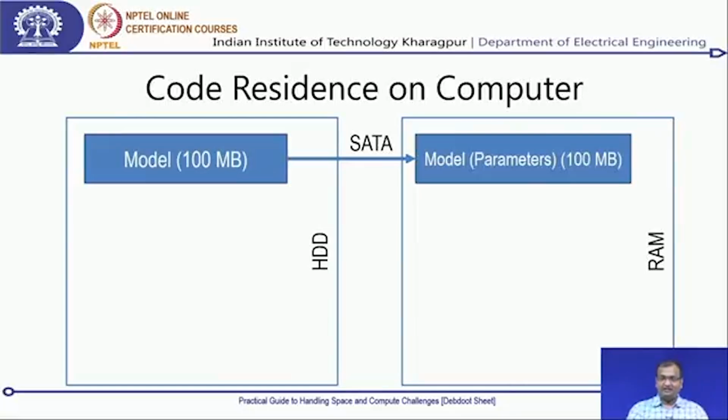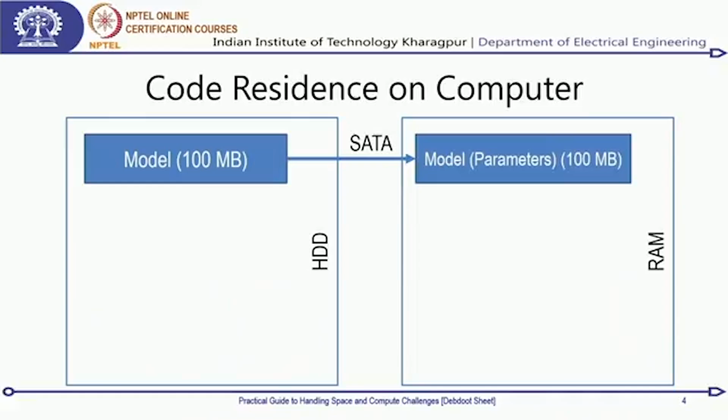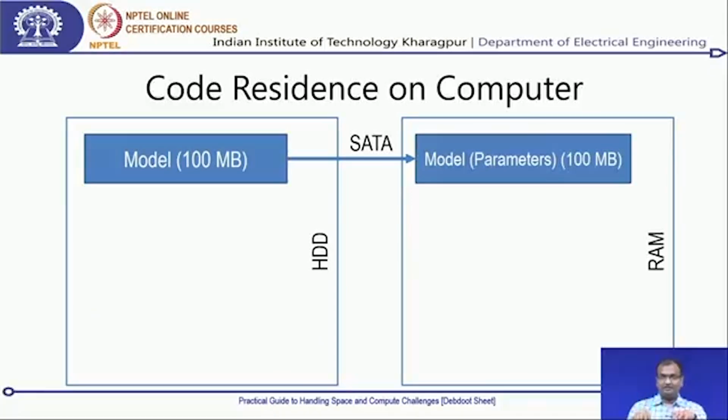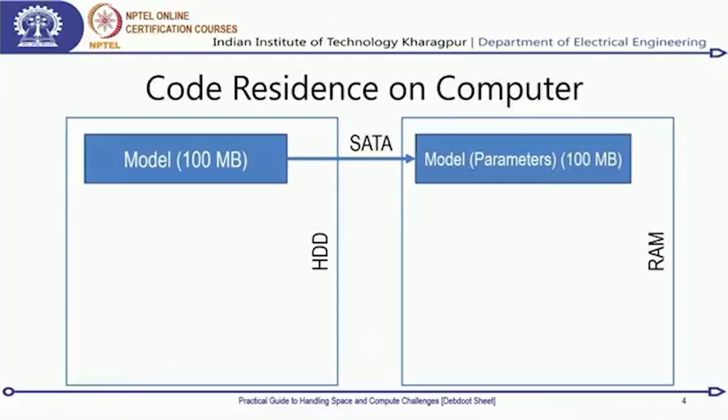So, what it essentially does is that there is a connection via a serial ATA. So, there is a SATA cable connection from your hard drive. It will be a thin blue colored or a black colored cable you would see, which connects from your hard drive onto your motherboard. Okay. And then on the motherboard there is a separate driver unit which is going to interface this protocol of SATA onto your RAM bus, which connects it back onto the RAM, and then via DMA transfer you can do all of this.